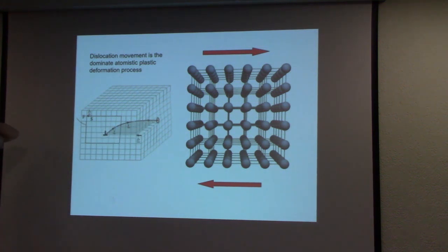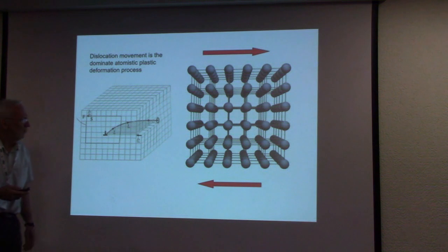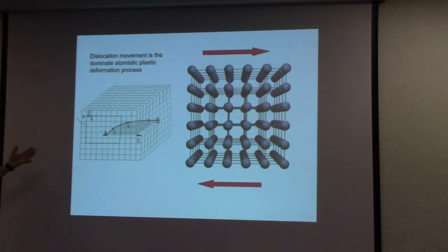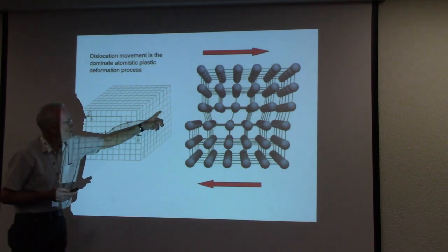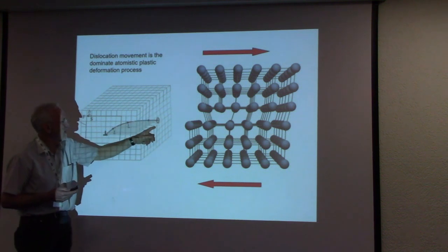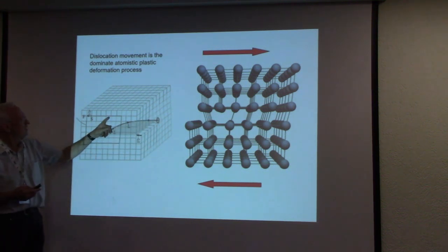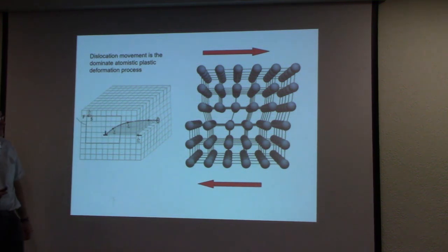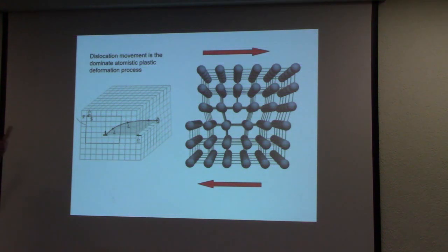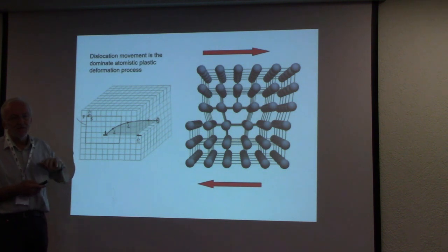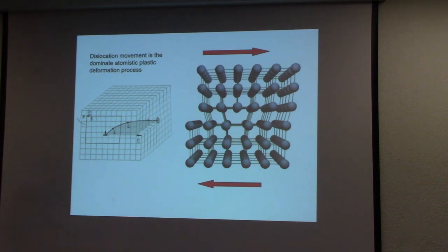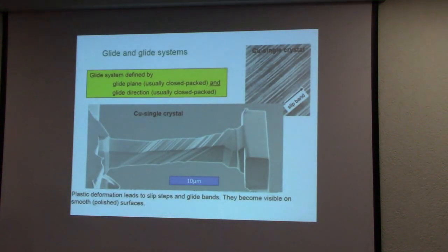This was realized 10 years later, or 8 years later, that a dislocation is not always such a single half plane. If you go around this crystal, you make a step. In this case, you have a missing area. This is the Burgers vector. And all the plasticity is caused by this movement of dislocations. There are millions or billions of dislocations which realize plastic deformation. Okay, good. This is an important point.